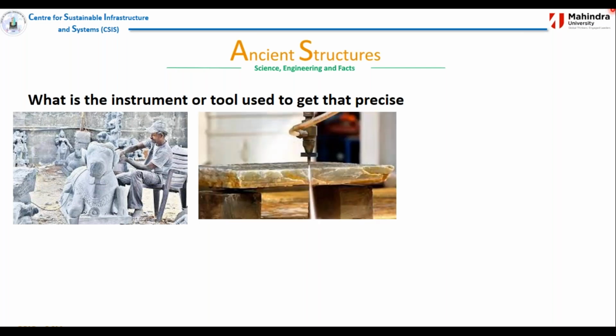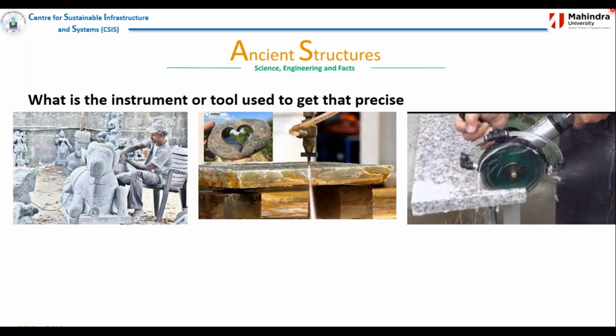And this is water cutting. They use high pressure water to cut the exact shape. And this is the love shape. So this is actually cut by water. The water gives a very fine finishing of the stone. But why did I keep this picture? Because if you see this one, the love shape, it can only cut exactly linear. You will not have non-linear cutting. You will only have linear cutting. And then you have other cutters.